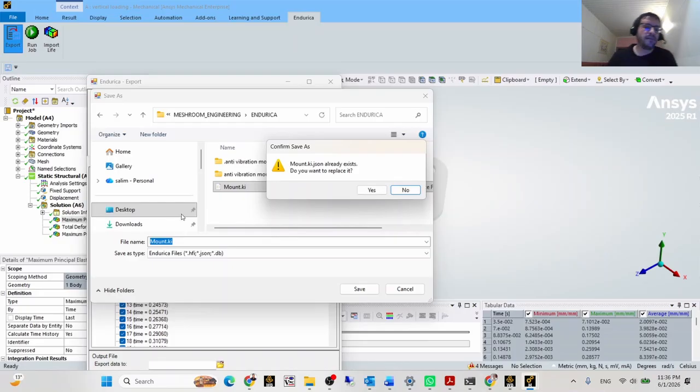If this one doesn't exist, I could have created a new input file to which I append only the strain histories. Later on I need to open that input file and add the headings, the outputs, the crack growth property model, the hyperelastic model properties, and so on.